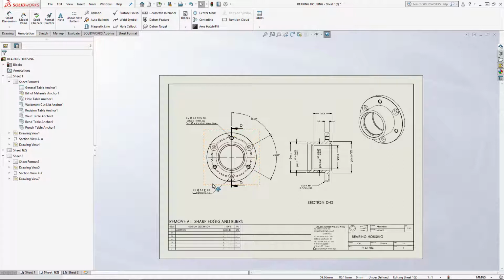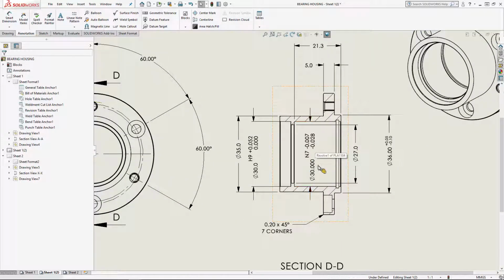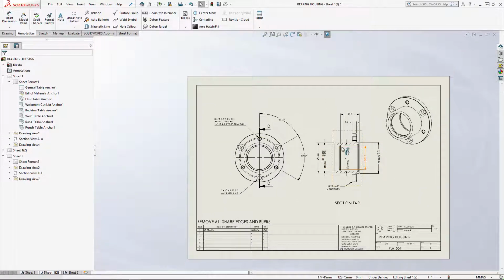We've looked at a little bit of how you might set up some part drawings, a little bit of how you might edit sheet formats, how you might link some of these values back to the actual part custom properties, and how it's best to set up tolerances within the part itself rather than trying to add them to the drawing, and potentially breaking the link between the definition that you model in the part versus the definition of the manufactured part.